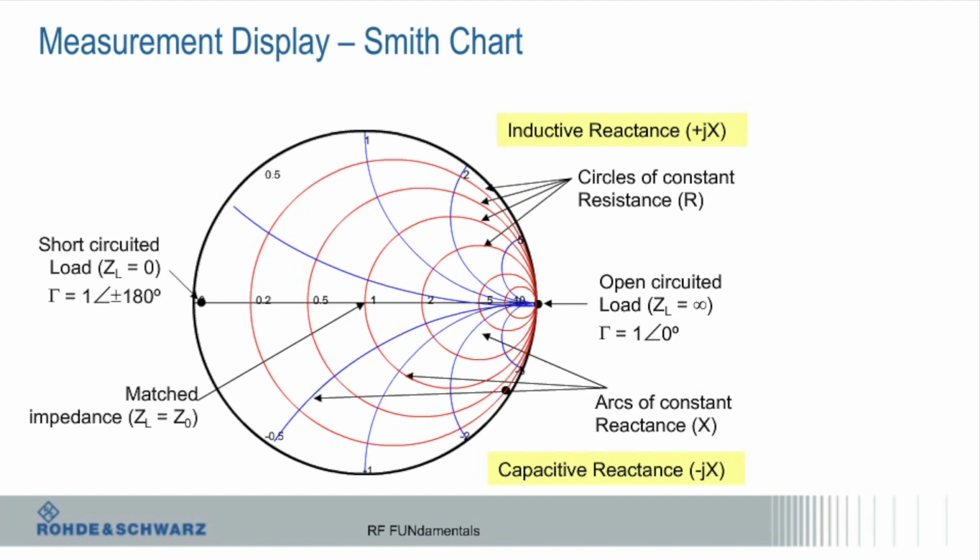So a couple things. First off, it has some electrical length associated with it, right? So that length is a function of frequency, right? So as you change the frequency, that length changes. So you can actually add delay to that measurement and move it to more or less a dot. But that's kind of the more general answer. The reality is, more so than even that, when I make any of these standards, do you think it's a perfect short from DC to 100 gigahertz? I'd be retired if I could make that, right? That's a hard thing to make.